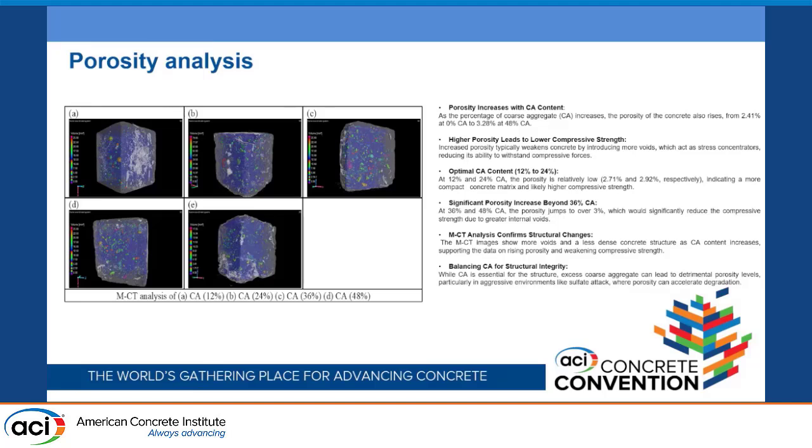This was one of the important and advanced techniques in which, unlike MIP analysis, which is common for analyzing the porosity of the concrete, we studied the porosity of the concrete at 180 days of sulfate attack, in which we put the whole cube of the concrete in a micro-tomography chamber, and we studied the porosity.